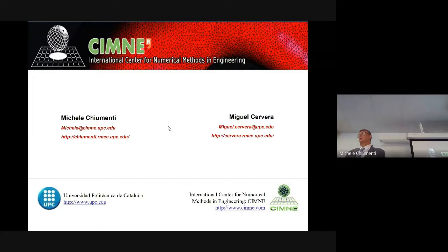So we learned about the particle finite element method yesterday, and there's also the meshing there. So could this be applied to the elements in PFEM? Yes. The element technology can be imported into any Lagrangian code, and PFEM uses a Lagrangian formulation. So this is not a particle in terms of discrete particles, it is a particle in terms of PFEM. Yes, exactly. PFEM is a sort of finite element method in the Lagrangian framework, including a movement of the mesh which follows the flow and whatever.